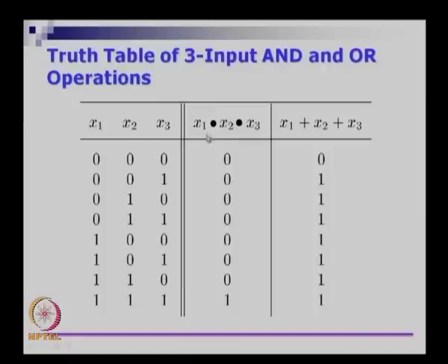If I have a 4 input AND function, first of all the number of inputs should be 4. Let us assume that's x1, x2, x3, another column added called x4, then you will have another dot x4 here, and the way it will be is you will have combinations starting from 0 0 0 0 all the way to 1 1 1 1, that is all the choices, and everything but the last row will contain a 1 for 4 input AND.